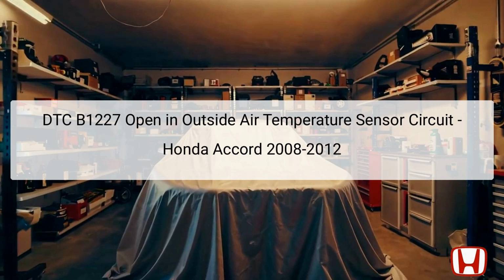Locating this sensor is essential. It is typically positioned in the front grille or near the front bumper of the vehicle. Proper functionality of this sensor is vital for maintaining efficient climate control and ensuring passenger comfort. When diagnosing this issue, it is essential to conduct a thorough check of the associated wiring and connectors, as malfunctions can lead to incorrect temperature readings, etc.